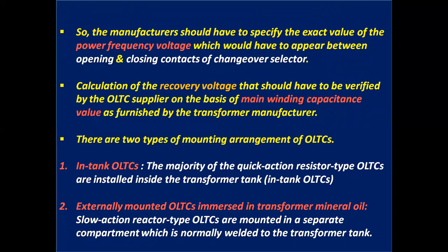So the manufacturers should specify the exact value of the power frequency voltage which would appear between opening and closing contacts of the changeover selector.